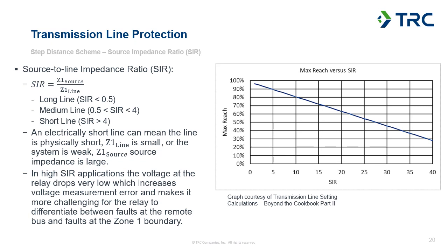And that's really a way for us to understand electrically what's going to happen, specifically with the voltage that the relay is seeing for various fault cases, and how that voltage divides between the source impedance, the Thevenin equivalent impedance behind the relay, and faults on the line.